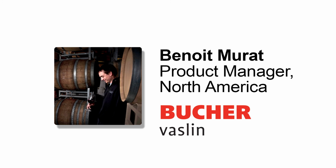So we say that we filter at 800 NTU maximum, but it gives you an idea, not necessarily. You have some surprises sometimes with low NTU and wine to filter. I would say, especially with Pinot Noir, because that's what we deal with a lot. And if you have a lot of beta-glucans in there, it's a problem. It really slows down your filtration.